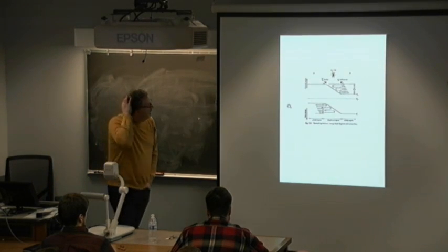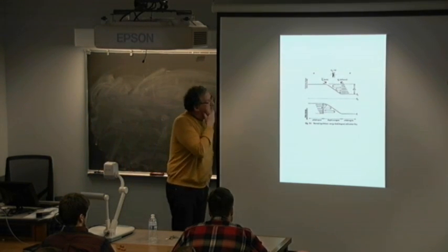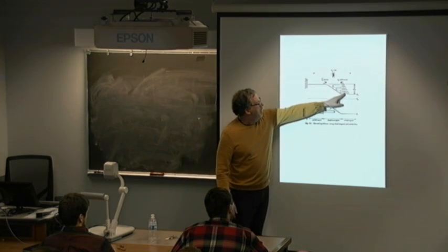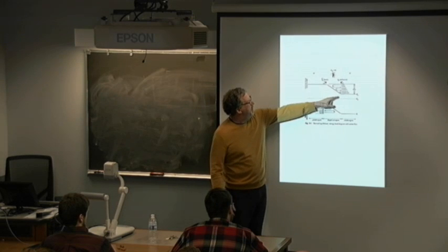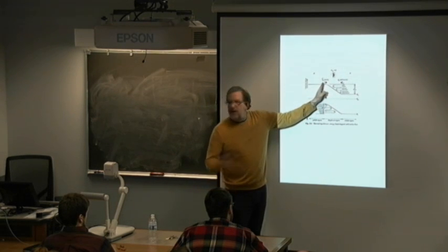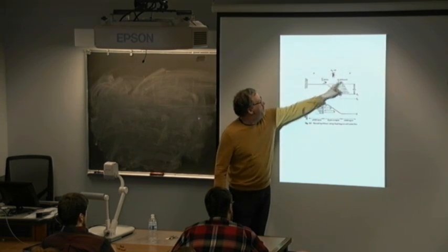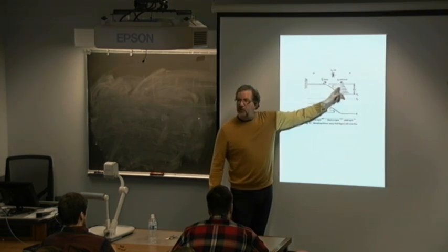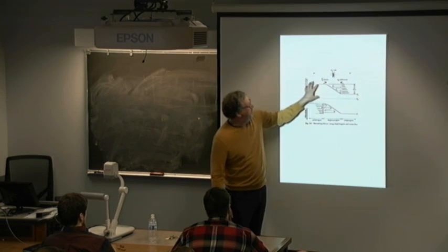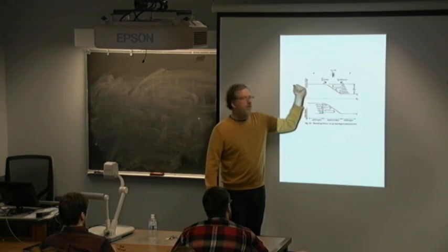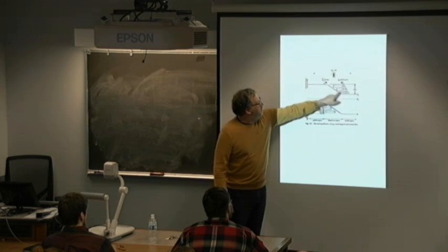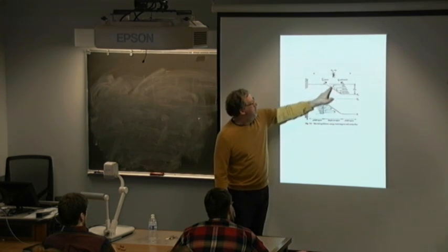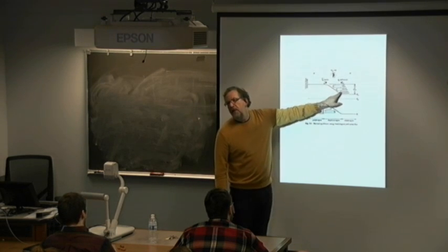Then I like this. This is fairly close, fairly accurate, right? It's a different representation of the same thing, but this is showing you the dynamic equilibrium. Drift and diffusion are balancing each other. The diffusion is driven by the concentration gradient, so there's a lot of electrons here, there's very few electrons here, so diffusion pushes them over here. But here there's an electric field, so these carriers are coming down the slope influenced by the presence of the electric field.